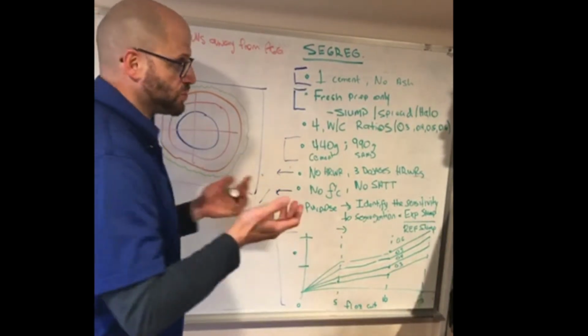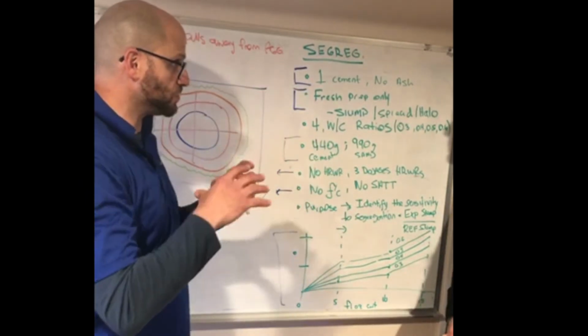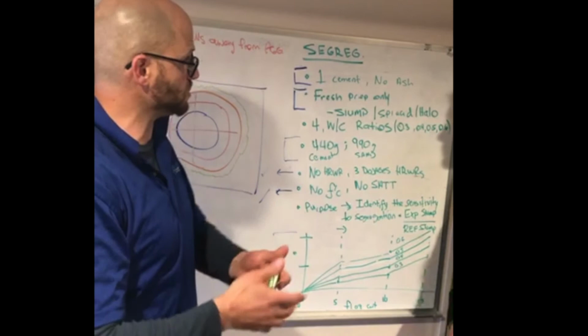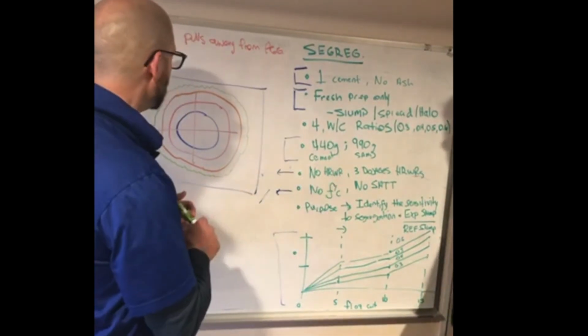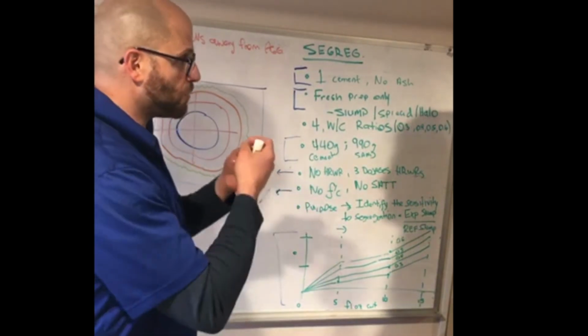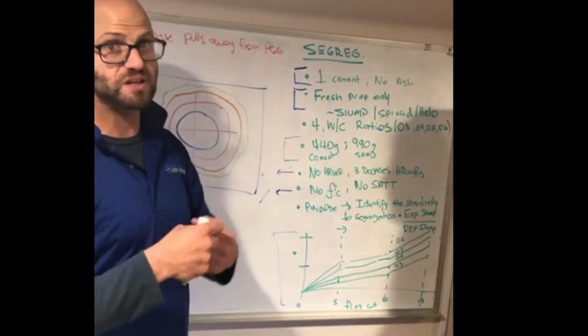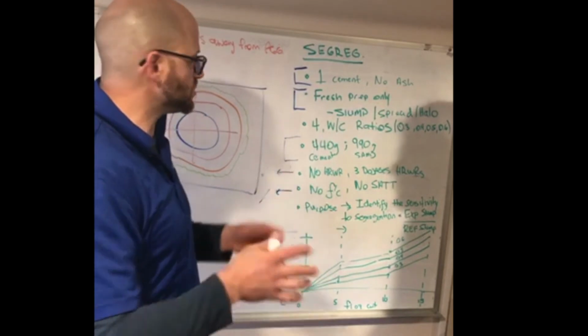Because basically what we're trying to do here is create a self-consolidating grout, a grout that consolidates under its own weight due to the force of gravity. And we're doing that by increasing water cementitious ratio as well as the high range, and that combination is what we're focusing on. But we could get to a certain point where our paste exceeds our granular skeleton, there's too much paste for the surface area, and then ultimately the paste just destabilizes.